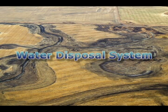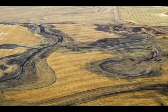Water disposal system. A complete water disposal system should be planned for each irrigated farm. This disposal system should be able to convey storm and irrigation runoff to an outlet without causing excessive erosion. It should be incorporated as part of the drainage design on lands that require or have a subsurface drainage system.